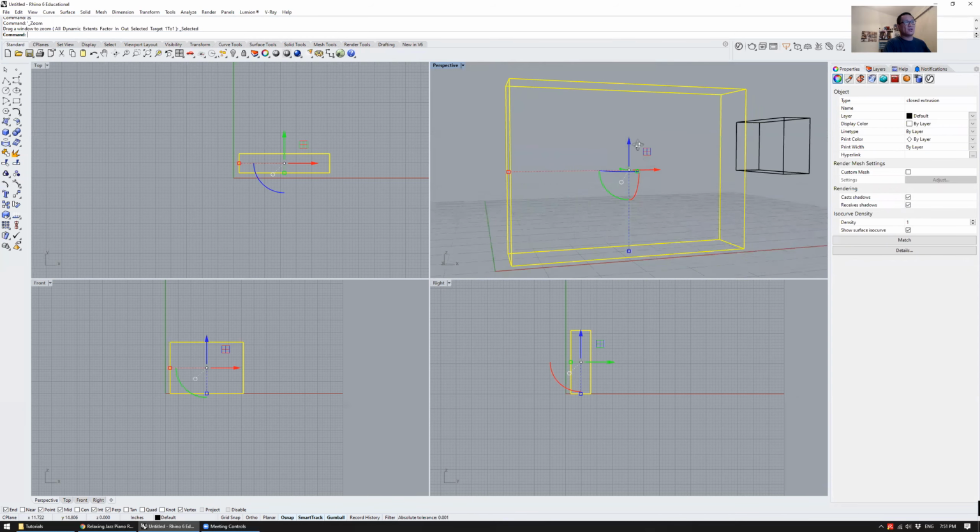So here I'm going to bring in, and let's say that you have some diagrams that may or may not look like this, that you are thinking of bringing into Rhino to work with, okay? I'm just going to select this one using the picture command, right? Open, and it will ask me to just plop it in. So first corner, I'll just pick a corner, and you'll see that it forces me to pick another size, just to get it into the Rhino interface, okay? So this is playing with your scanned diagram right now.